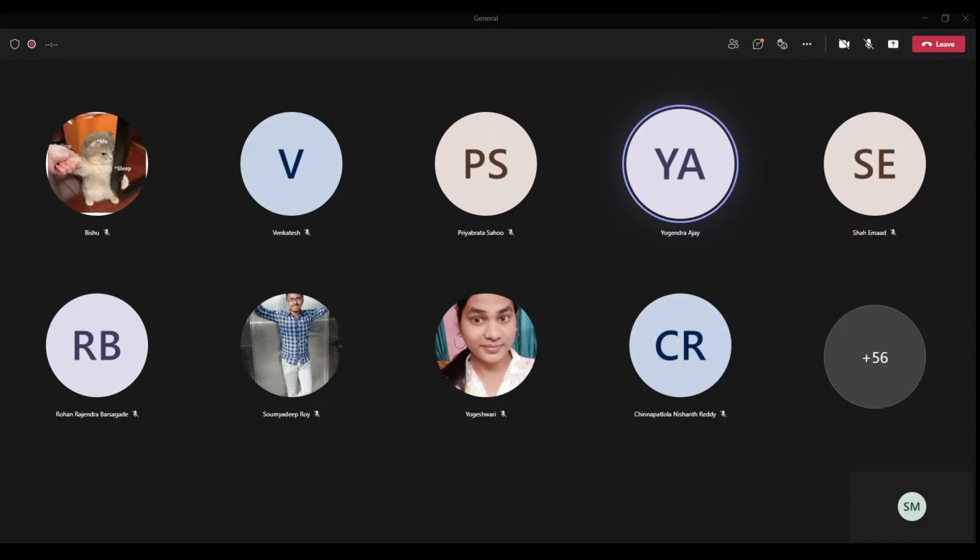And there's a comparator circuit over there. Based on the output given by the receiver, you can tune the output which you get. Let's say you tune the potentiometer in such a way that for a particular strength of radiation, say X, you get a high.